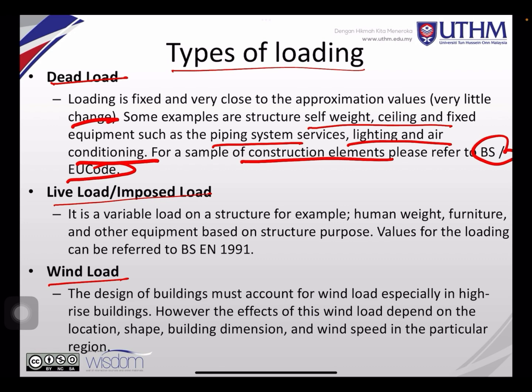Live load, or imposed load, is variable load, meaning it changes from time to time. For example, human weight, furniture, sometimes you do change the location of the furniture, and other equipment based on the structural purpose. Values for the loading can be referred to BS EN 1991.